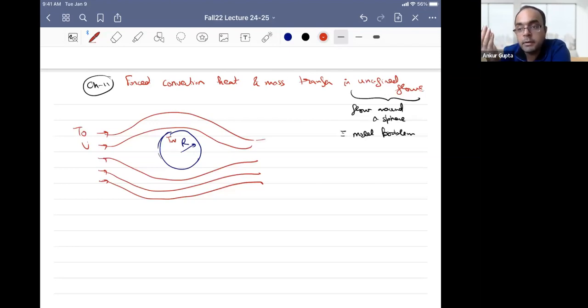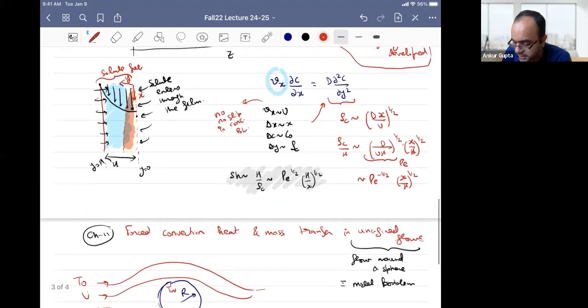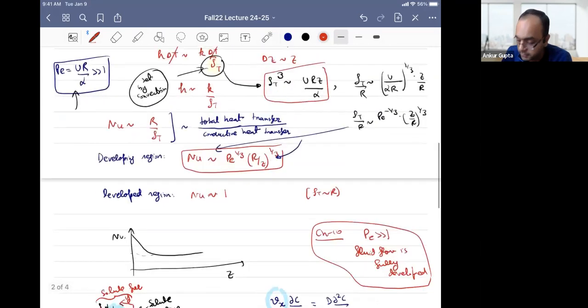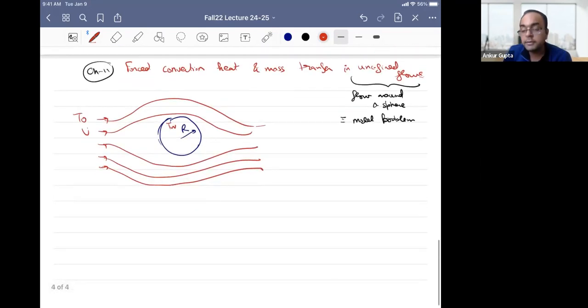It can have different formulas. So we have two steps here now. One is to solve the fluid flow, and one is to solve the heat transfer. And at the end of the day, all we will be doing is trying to calculate the scaling analysis for Nusselt's number, like we were doing for Sherwood number, which is basically Nusselt's number in solute transport. And all we want to do is to understand different scaling analysis for Nusselt's number here.